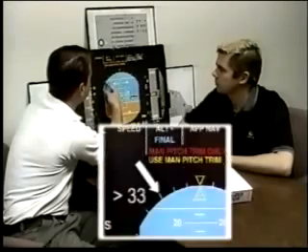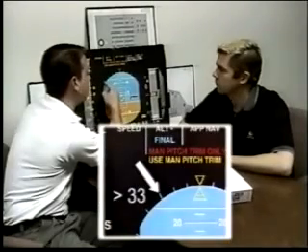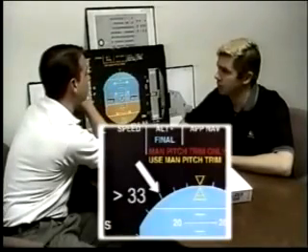Okay, let's assume that you're in high speed protection, you've commanded 45 degrees bank, and you let go of the side stick. What occurs? If I let go of the side stick, the aircraft is going to roll back to 0 because what it's trying to do is protect itself from over-G'ing asymmetrically. What about on the low speed end when you've commanded 45 degrees bank and now you let go of the stick? In low speed protection, it's just going to roll back to 33 degrees because it's not concerned about the over-G. Okay, so with that in mind, any bank angle that's greater than 33 and you let go of the side stick, what occurs? It's going to roll at least at 33 degrees.